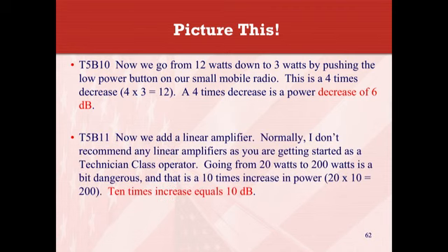Now we add a linear amplifier. Normally I don't recommend any linear amplifiers as you're getting started as a technician class operator. Going from 20 watts to 200 watts is a bit dangerous, and that is a 10 times increase in power. 20 times 10 equals 200. A 10 times increase equals 10 dB.